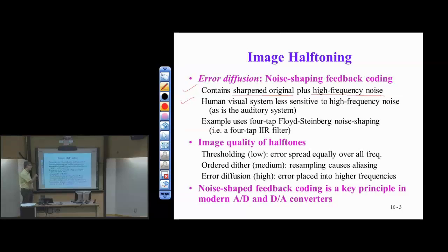The example that I showed on handout J is a very simple feedback. The filter in the feedback loop only has 4 coefficients. It is very simple to implement. Those coefficients are all powers of 2 or sums of powers of 2, so it is very simple to implement in any sort of system for high-speed display or printing. Now, it's actually an FIR filter, but because it's in a feedback loop, it behaves as if it were infinite impulse response.